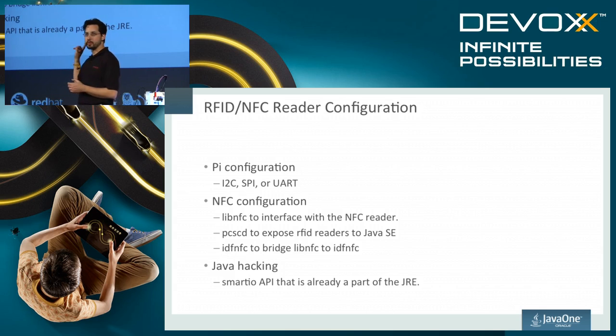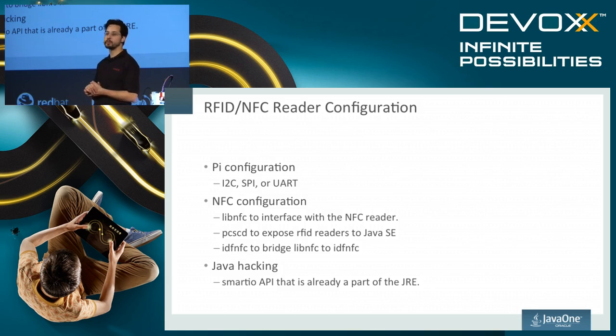But to access the chip directly, you have to use a library like libNFC. So I'm using that to talk directly to the chip. And I tried all three interfaces, I2C, SPI, and UART. Apparently there's a bug on a bunch of the chips where I2C support doesn't work. The address fluctuates randomly. So on my particular RFID card, SPI and UART were the only available interfaces. I2C was buggy. Although your mileage may vary, I2C is supposed to work on these boards. So I think that was just a bug on a certain number of them which came out.